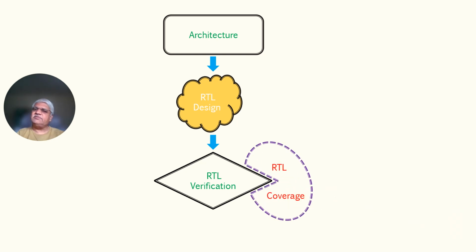In the case of dynamic verification through functional simulation, input vectors are provided to the RTL design, and a test bench is created. The expectations as part of the specifications state that the corresponding input vector should yield so and so output results.